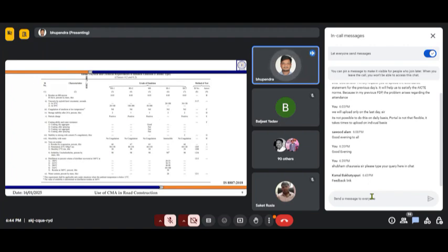After that, all these tests are for checking the quality of your bitumen. So coagulation is checked at low temperature. Coagulation means whether all these suspended bitumen particles are getting grouped together or not. We don't want that. The coagulation should be nil. Storage stability also is a test that we check in percentage, like 2%, 1%. Then the particle charge is positive, because we are talking about the cationic type of emulsion. Coating ability is also checked, and then stability to mixing with cement,